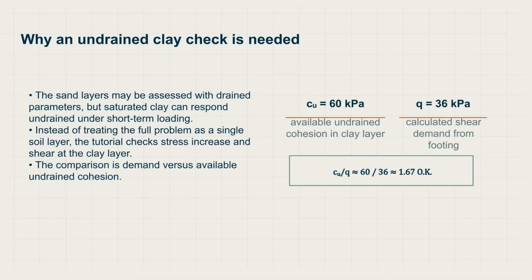An undrained clay check is essential for saturated layers under short-term loading. Comparing the shear demand of 36 kilopascals against the available 60 kilopascals gives a ratio of 1.67, confirming the design is acceptable.